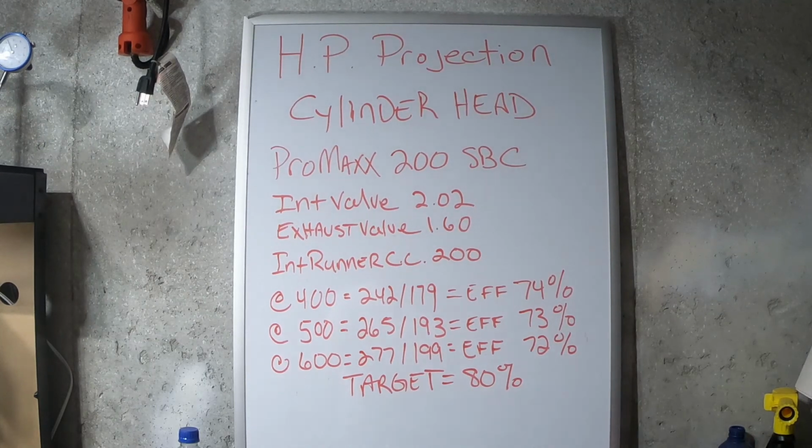Go ahead and port the exhaust ports. Make them a little bigger, make them smoother, let the air get out a little bit quicker. That's going to increase the efficiencies. And then what you can do mechanically to increase the head efficiency is select a camshaft that has a dual profile. You'll look at cams and they'll have advertised lifts, and a lot of them are balanced. They'll be like 450, 450, 480, 480, 500, 500. Intake and exhaust are both the same. Those are single profile cams.